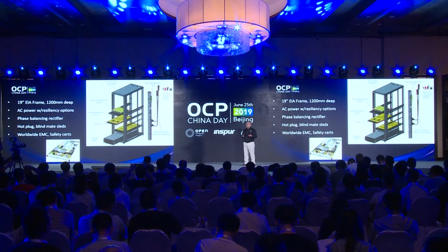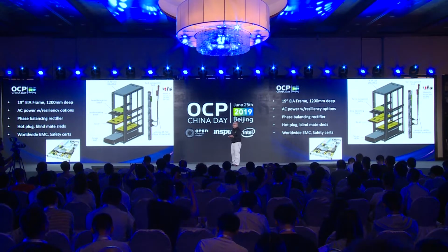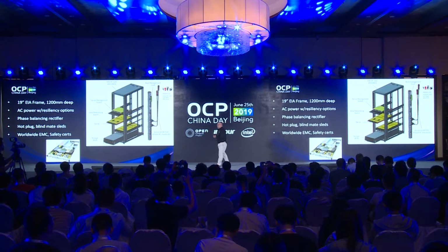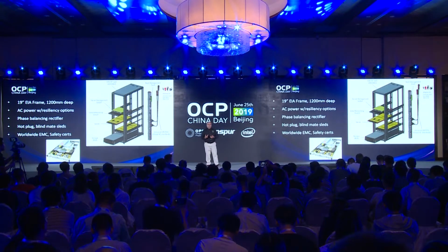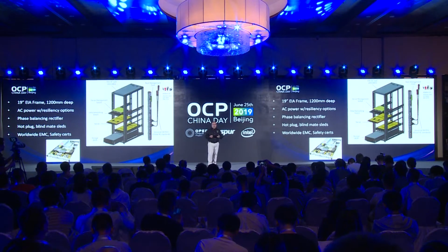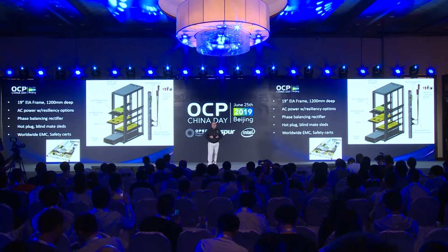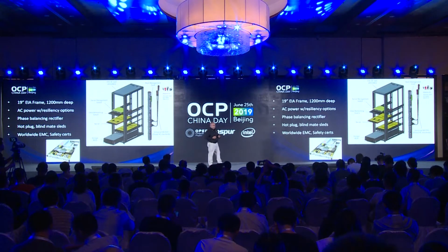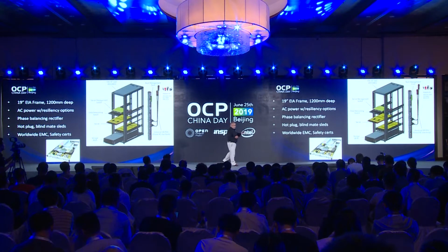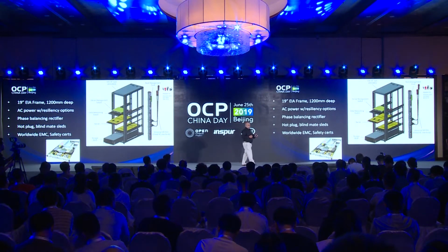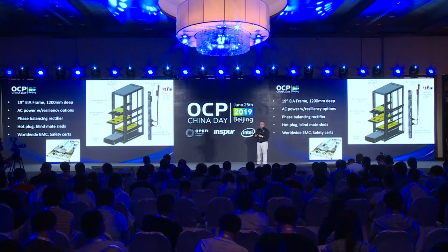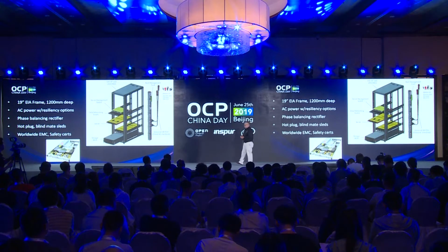In a three-phase utility feed today, a lot of times we convert each of those phases and produce a DC output or an AC output, and those AC outputs can become imbalanced. With a phase balance rectifier, you're able to have the exact same current loads on all three of those phases. All of that was built into this silver box, into the power supply that's in Project Olympus.